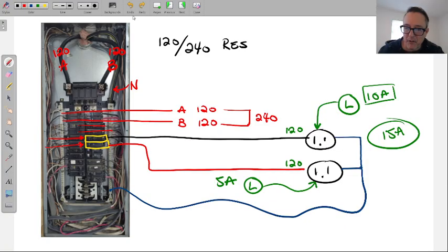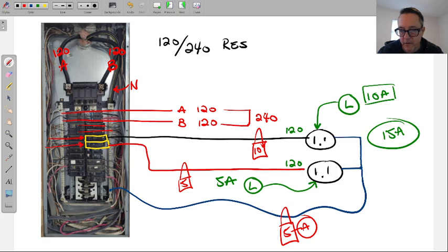That's okay. If I measure this with my meter, I'm going to measure 10 amps here. If I measure this circuit along the line anywhere, I'm going to measure 5. But then when I measure the neutral, I measure 5 amps as well, because this is the job of the neutral: the neutral's job is to carry the unbalance between loads.